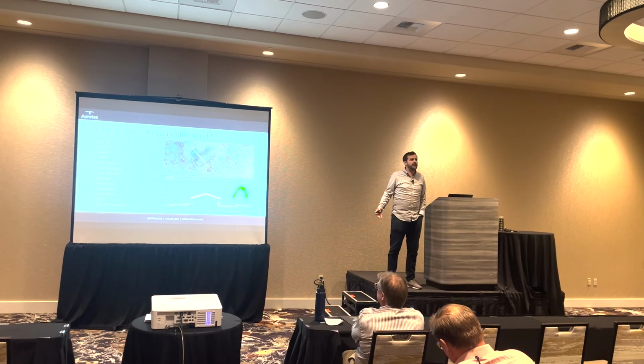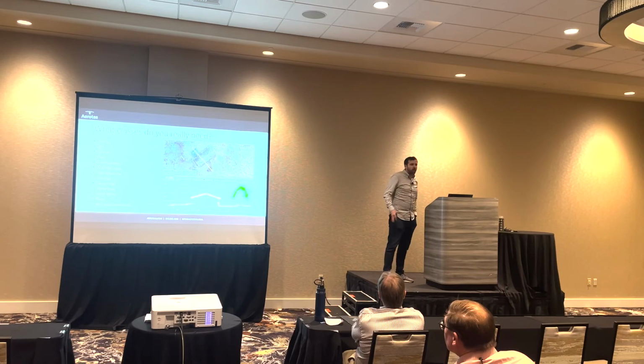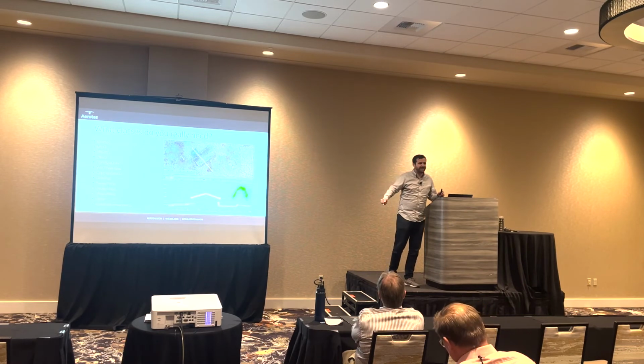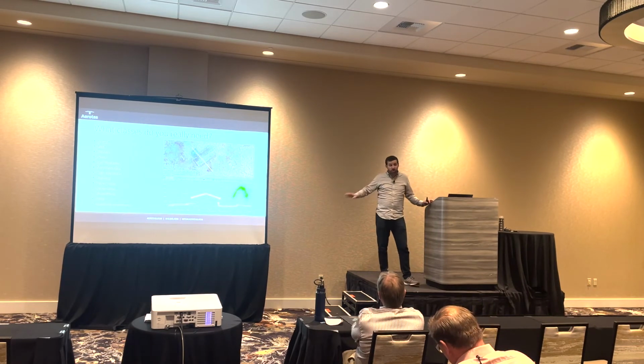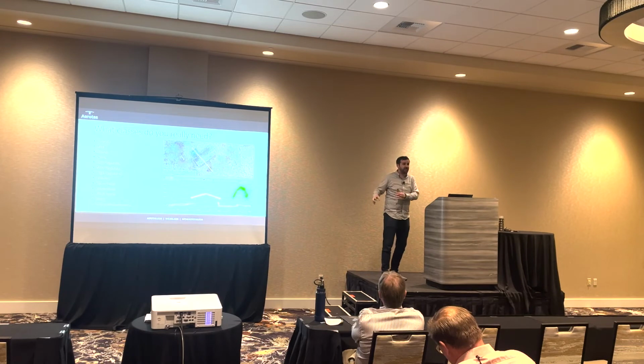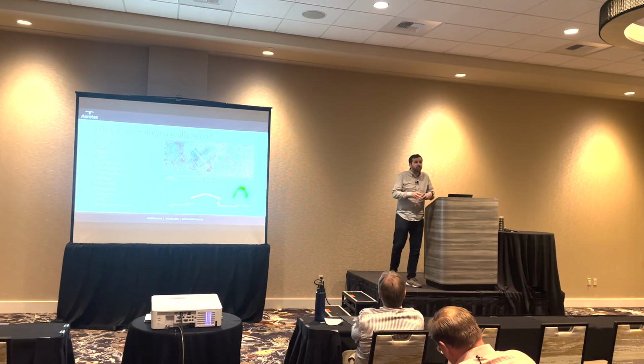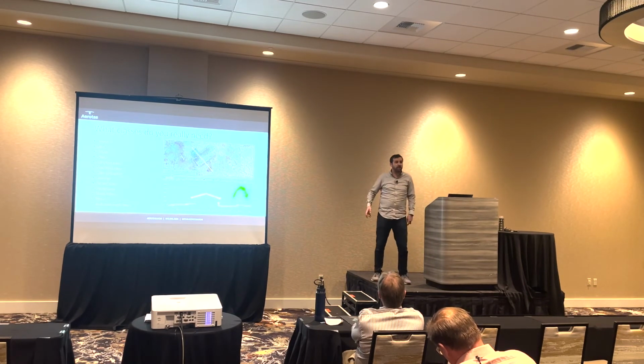As I said at the beginning, your goal should be to get what you need and get out. For the majority of our LiDAR projects, there are only two classes that we use, ground and not ground. That's it. For the majority of our projects, ground and not ground, and we totally ignore everything else. Because we're there for topo. And that's why we're using the LiDAR data, to create a clean topo. We're not there to model power lines. When we do need to model power lines, that's what we do.